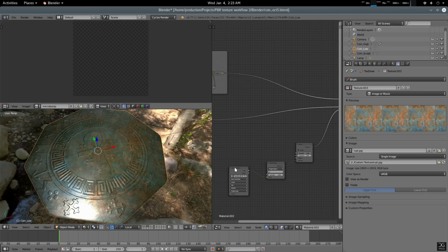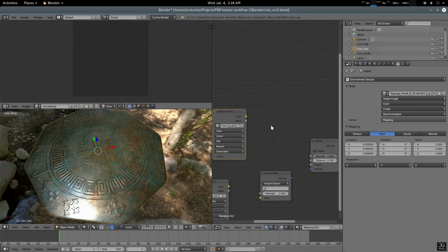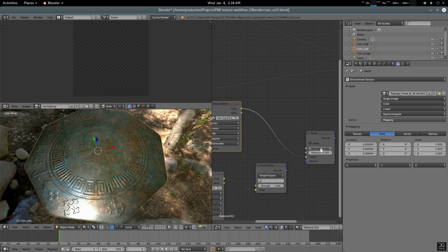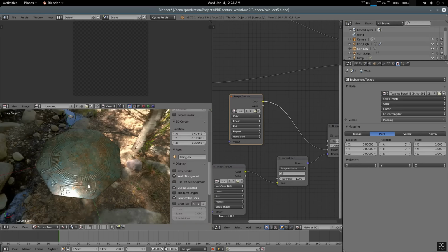Just go to Shift D. It should be a color data, and let's go to micro bump and hide it. With that, use some kind of strength, like, we can adjust it later, so 0.2 something. Yep, let's go to texture paint again, press N, sorry, T.